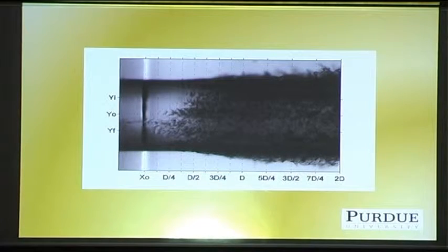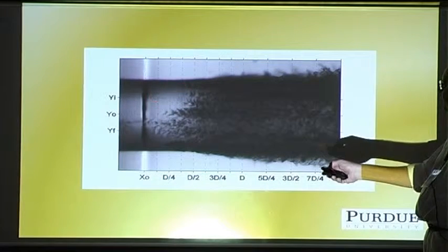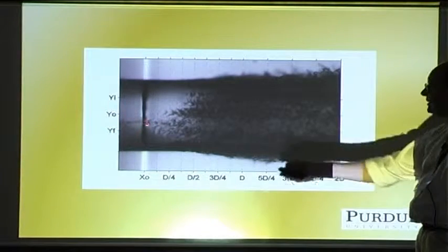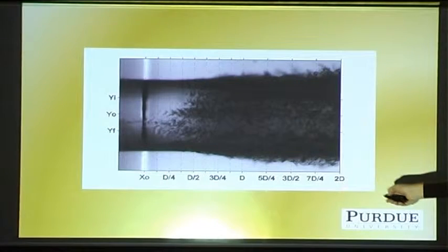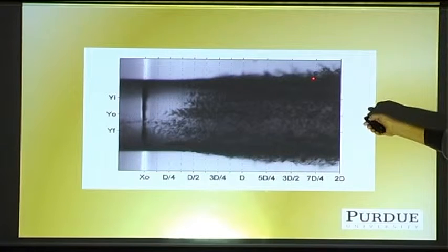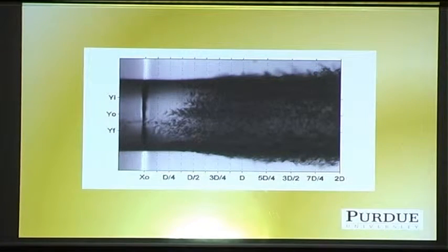And there's one where a lot of fun stuff is going on, again with the thick boundary layer. And some laminar regions here, other regions, it's coming out of the nozzle turbulent right here, okay? And obviously, if you were looking at a cone angle, you'd see that there is an angle here and there's almost none on the other ones. Ligaments up here are already forming and throwing off from the jet.